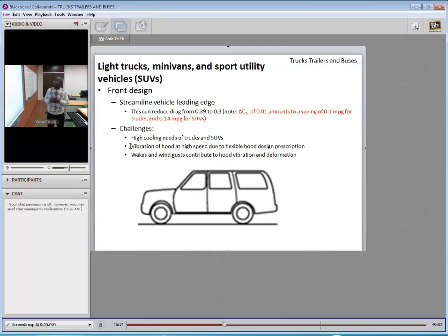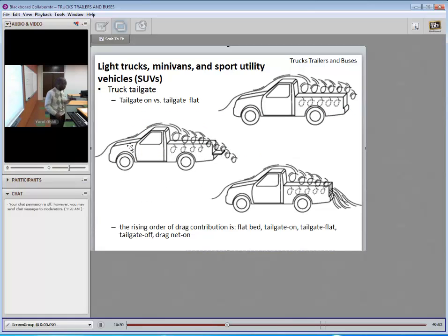One of the things that has been done to make that contribution is adding stiffeners at different locations in the vehicles. So hopefully with the stiffening, the now thinner skin can still maintain the rigidity that it would have had if it was of a thicker design. That used to be the case.